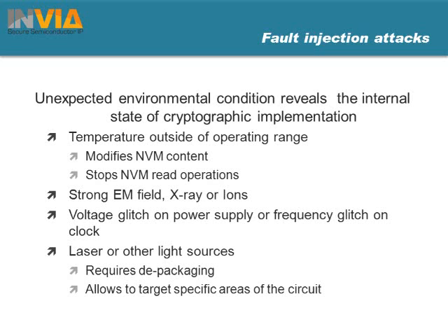And then laser, although this one is much reported in academic publications, and there are lots of articles on attacks based on laser or other light sources. It's not that easy to mount because it requires depackaging. And depackaging is already a step that costs some money. So if you can do stuff without depackaging, like voltage glitch or like the side channel attack that we saw previously, that's a much easier attack to mount, and the easier the attack, the more attackers you get.